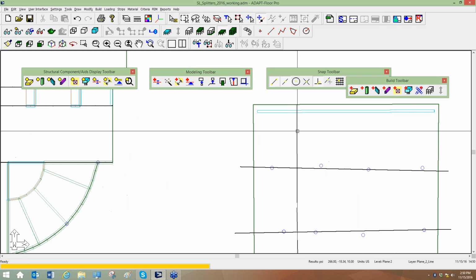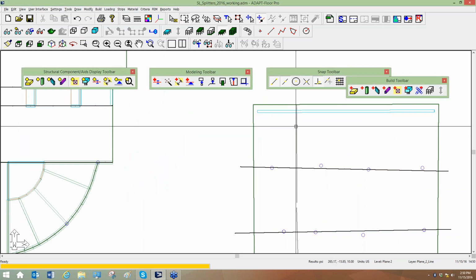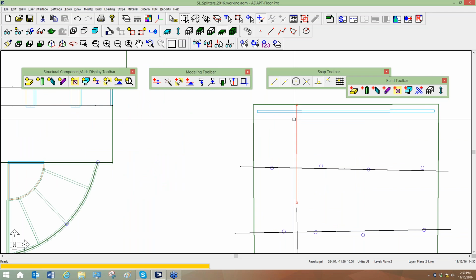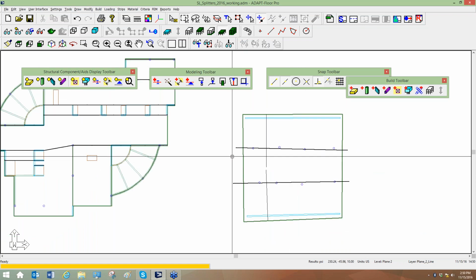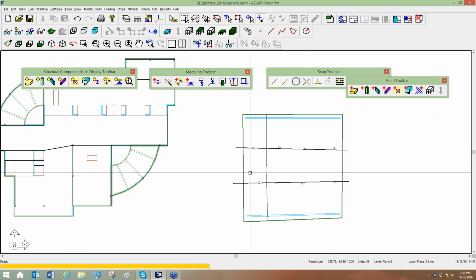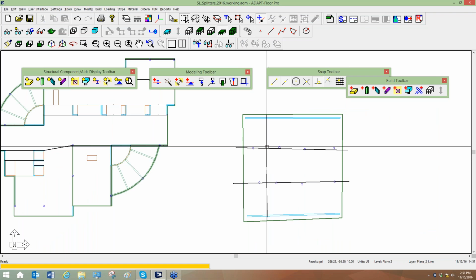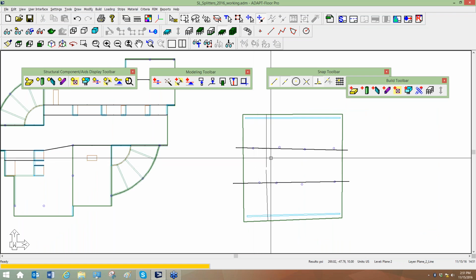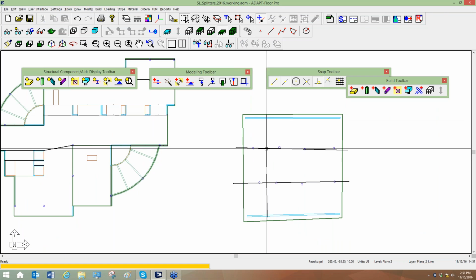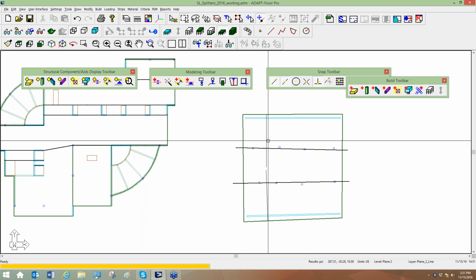When a design cut extends over a wall, the program does not report stress, number one. It doesn't design for reinforcement at a strength level for design cuts that extend over a wall. So in this result, I would get 0 rebar for strength purposes. I would get no stress check, and I'm integrating over a zone that goes from, let's say, positive bending, and then it creeps over to negative bending. So the net effect is very coarse in terms of the result, right?